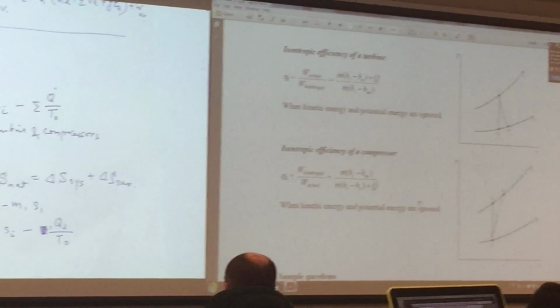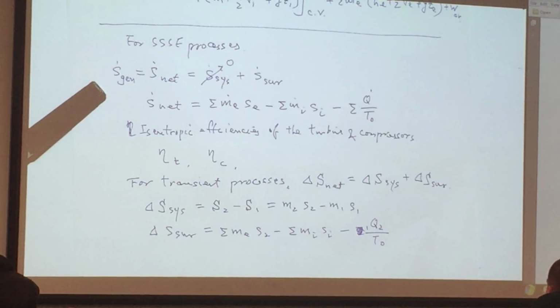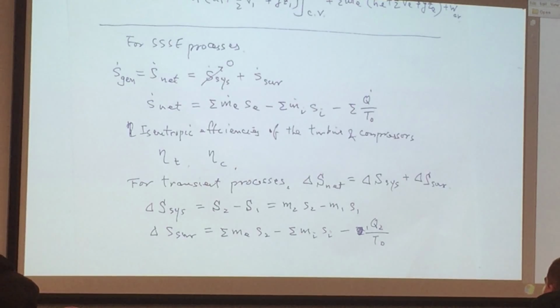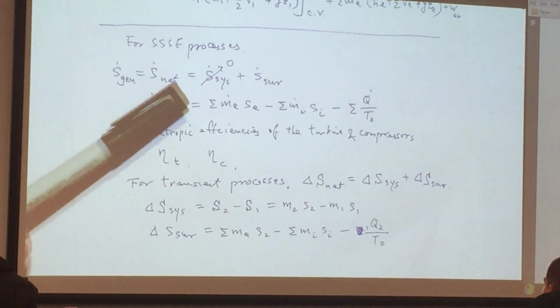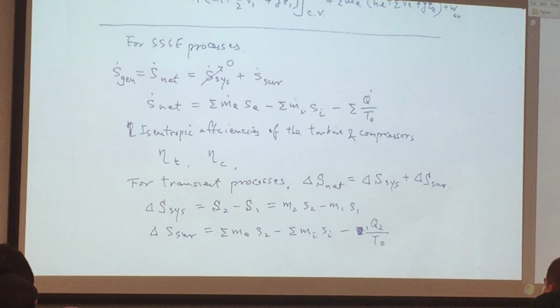And then to calculate the rate of entropy generation, this is for a steady flow process. We know that there is no mass accumulation in the system. That's why the system energy change is zero. The system property change, energy change, is zero. So we can only measure the mass flow rate. That's why all the terms are in rate form, unless you divide all the terms by the mass flow rate, and then that will become specific entropy change, specific internal energy change.